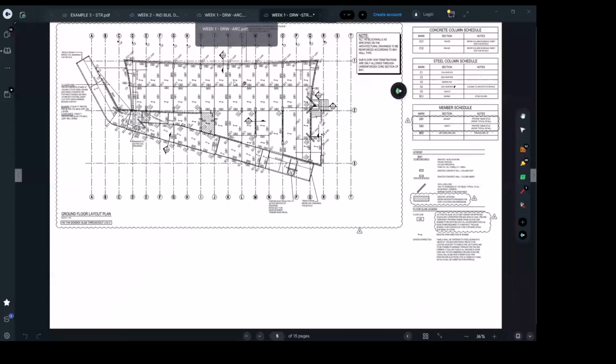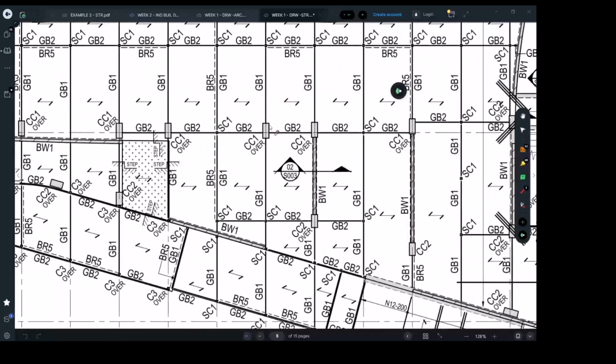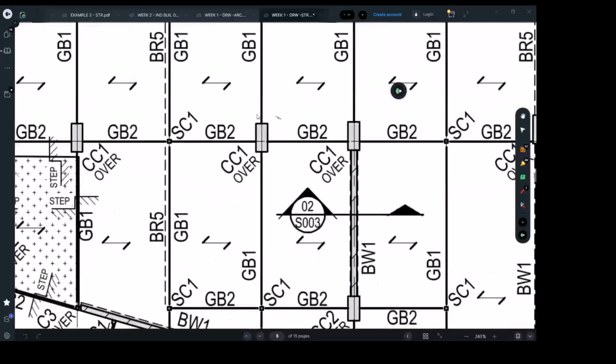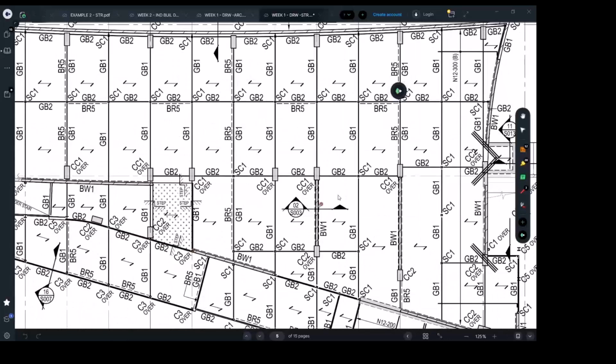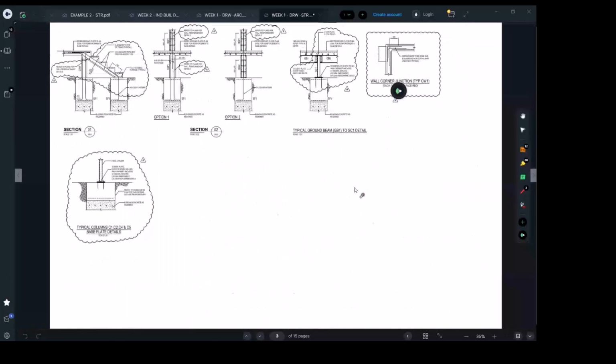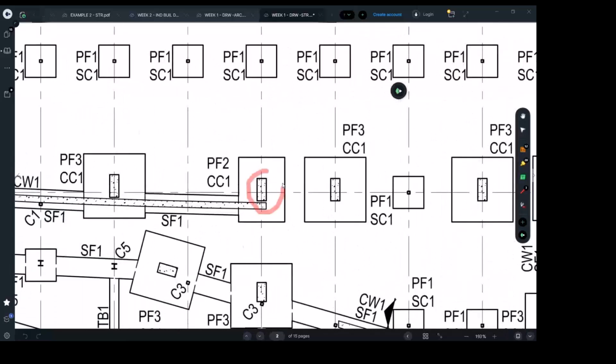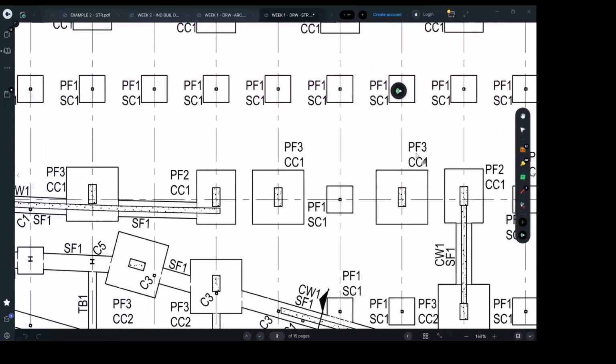I remember some students were saying to me, it's gonna take the load to the ground floor. No, the ground floor is elevated. So you see the columns, they are actually going through the ground floor, which was a special elevated floor. And then it will, you can see there are details which helps you here. How the concrete columns, you can see these are the pad footings. So each column, the CC1s, they got their own decent pad footings, the large ones.